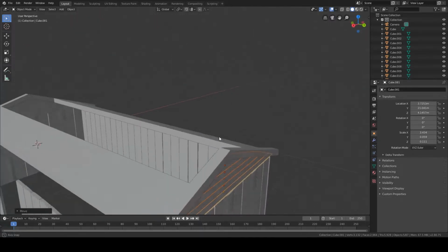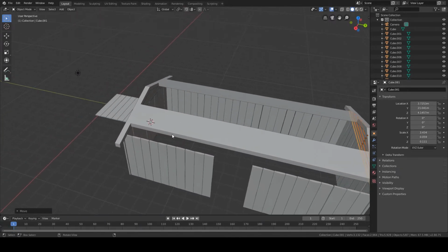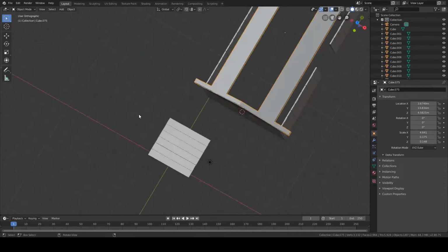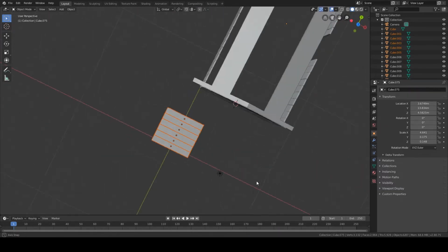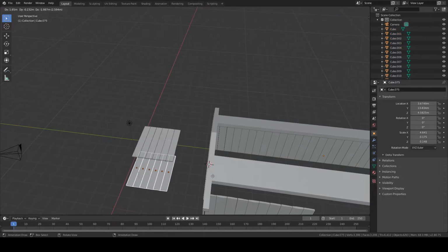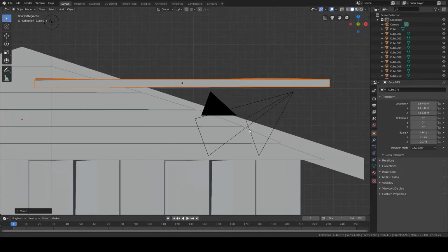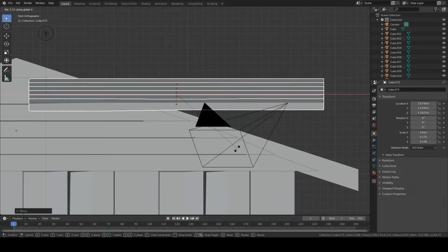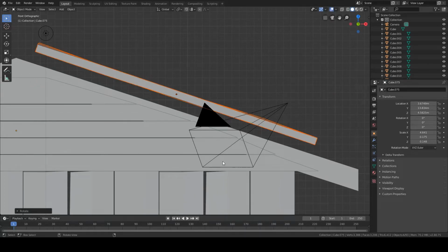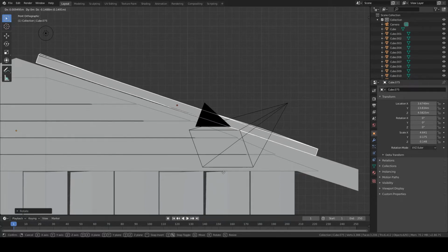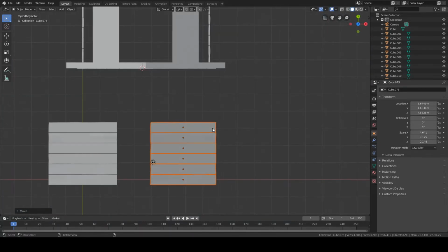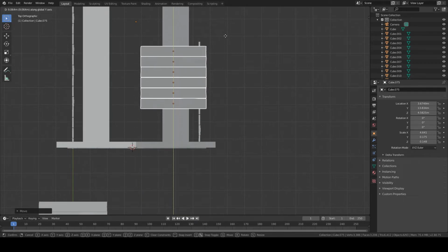Okay, great. Now we just need to go ahead and make a roof. And for the roof, we're going to just do some shingles straight down. So we're going to actually go ahead and just use these that we already have made. We're going to just highlight them, Shift D to duplicate them, and then we're just going to put them in place. We'll press R to rotate them on the Y-axis. I'm going to press 7 on the numpad to line them up with our building.